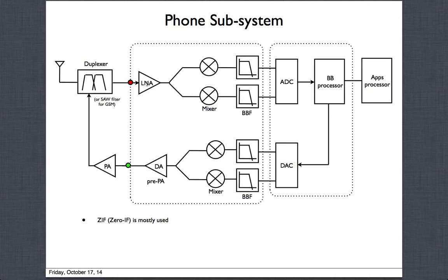Gain programmability is also in the LNA, because we have to handle a wide dynamic range. So you have to have gain programmability at various levels, at the various stages here.